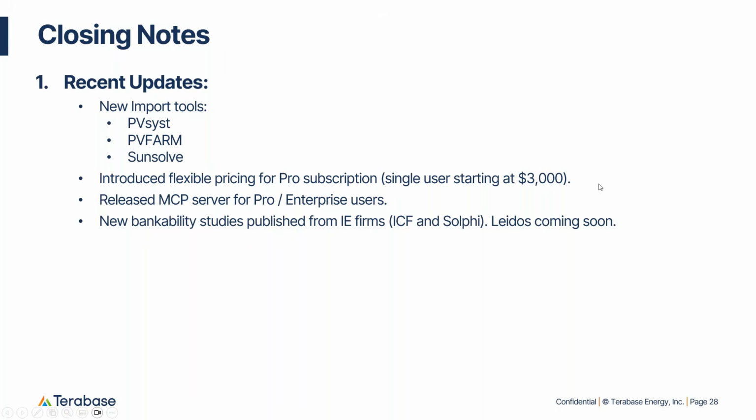There was a question about sub-hourly: can we bring in sub-hourly data from PVsyst, and does PlantPredict use the adapted Perez transposition model for sub-hourly modeling? So yes, we can bring in sub-hourly data. No, we do not currently use that adapted Perez model that was introduced in version 8.1 of PVsyst, but Solfi did do a comparison of PVsyst versus PlantPredict, given that new introduction of the sub-hourly model on the PVsyst side. So I would check that out.